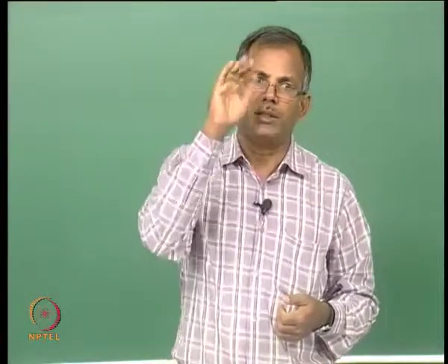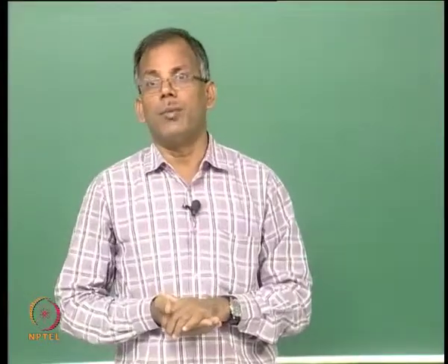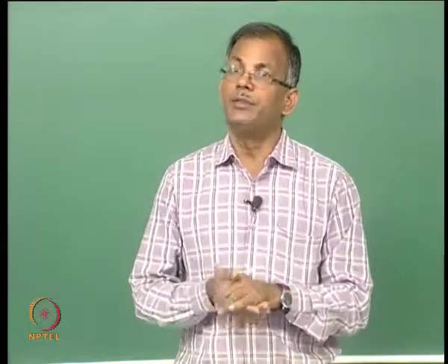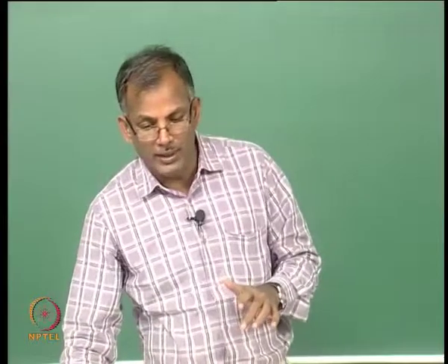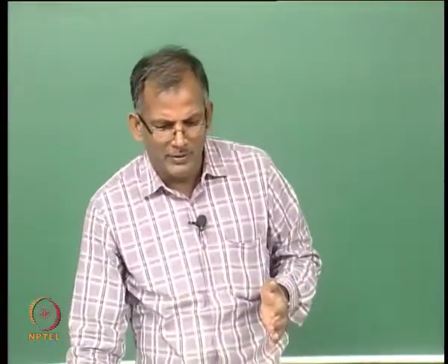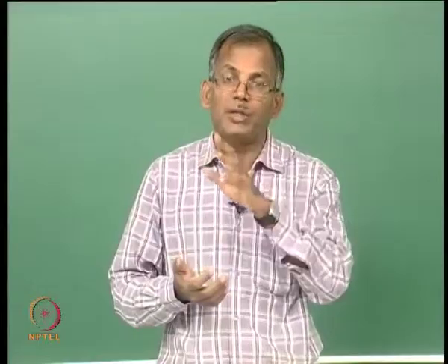So, that is one very important thing that you need to remember. It is not only the yield strength that reduces, but two things happen. There is a reduction in the modulus, and also the modulus is not a constant value throughout the range of deformation, it is going to be changing, which needs to be accounted for if you are using higher strain values. If you are using 0.2% strain, you need not worry, because the difference between this and this is probably very small, but if you decide to go for a large deformation because you want to absorb more energy, you want to allow more strain, then the strain values need to be appropriately taken to calculate the modulus of elasticity.